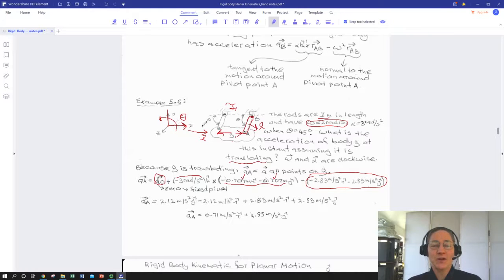So as soon as we put x increasing to the right and y increasing upwards, we define counterclockwise as positive for omega and alpha. So since we were told they're in actuality clockwise, we have negative values for them both.